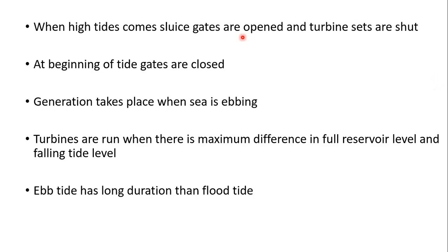Okay, so this single tidal cycle system requires a deeper reservoir. So we have to locate the sluice gates as deep as possible. If you go for a deeper reservoir, its construction will be of greater constructional cost.